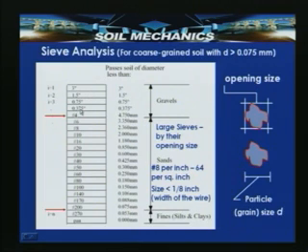The sieve number is indicated by the size of the mesh itself, that is up to 4.75 mm. You can see here 0.375 inches is the sieve number, and the particle diameter equivalent is also 0.375 inches. So, this is in the range of the gravels, and from 4.75 mm onwards to 75 micron size, the sieve numbers are indicated, categorized like number 4, number 6, number 20, number 100, number 200. Number 200 indicates the sieve number for 75 micron particle size.